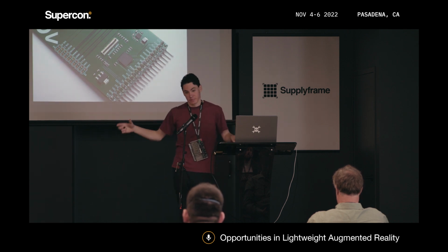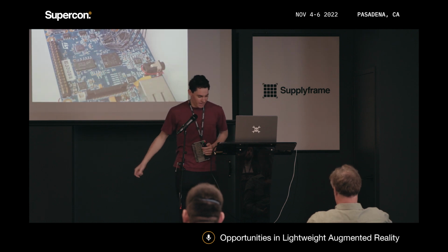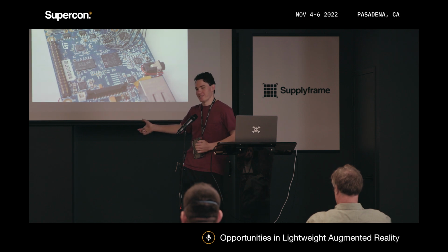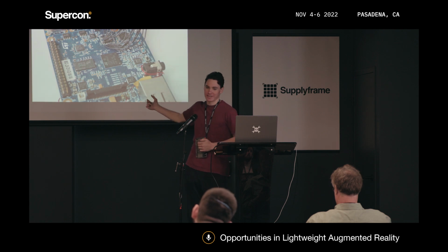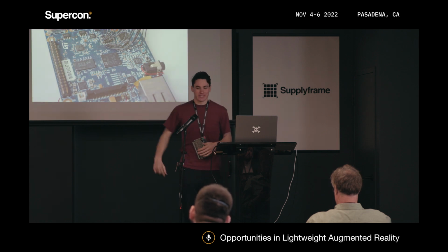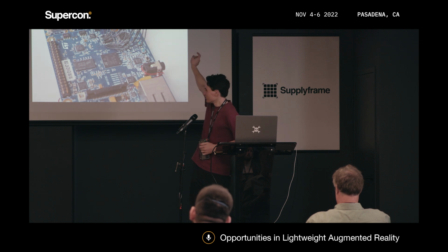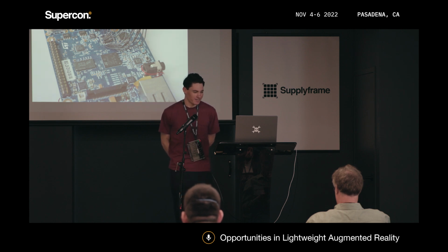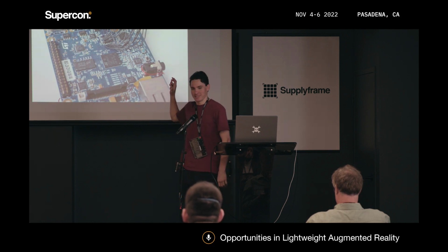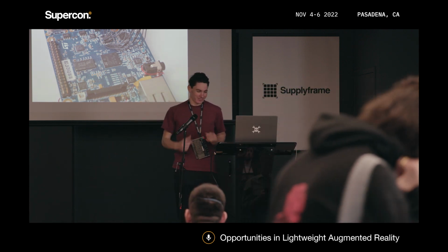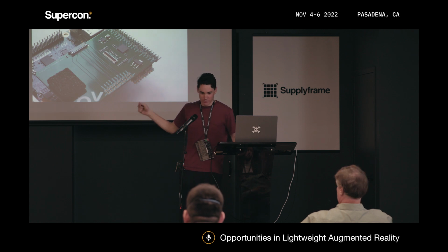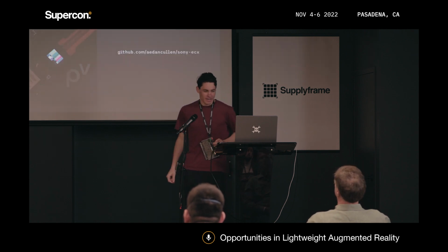I wanted to test this with that STM32MP1, for which I had a development board, of course, but they don't expose the parallel LCD interface. Instead, they feed it to a chip which is an HDMI encoder. I don't want the HDMI encoder, so I just remove it, and then you solder up your wires to get your parallel LCD interface. This is what I do when I want something to work now, and I don't like how the evaluation board is designed. Then my little test board with the bridge chip stacks on top, and the display works.